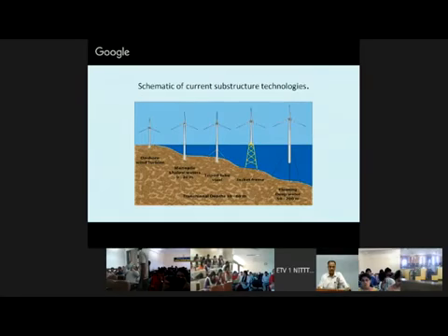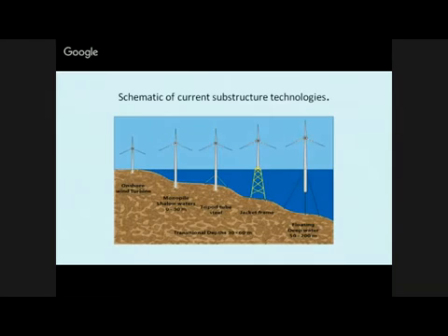the sea: marine biofuel can also be produced, then wave energy is there, tidal energies are there, and offshore energy is there. So through the sea, the next decade will belong to this particular zone. Now, the point is about foundation technology. You will see that where the sea depth is less, you can use a monopile, and when the sea depth is higher, you can use a tripod. Then you can use a jacket type for that purpose. If the sea depth is between 50 to 200 meters, floating type wind turbines are used, and floating types are still at a developing stage and quite expensive.